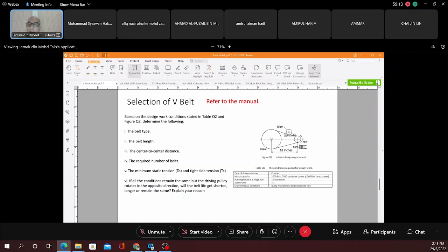If you don't see it, I have an idea. Take a rubber band and rotate it with your finger. This side is going to be tight, and the other one goes a bit down. That means this is the tight side, and this one is the slack side. So your idler will be positioned at the slack side.